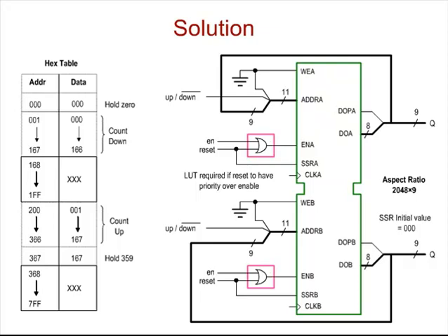One of the concerns is the priority of the control signals. In our case, if the reset is to work, even if the enable is low, then you need to have the additional LUT to resolve this as shown. This design could support an additional control input, the MSB of the address, or you could use this to perform the reset and save the external gate feeding the enable inputs. But this would mean that the enable had to be high for the reset to work, and you could do that with the dedicated SSR pin anyway. You could move the enable to the MSB address, and this would allow the reset to have the highest priority.